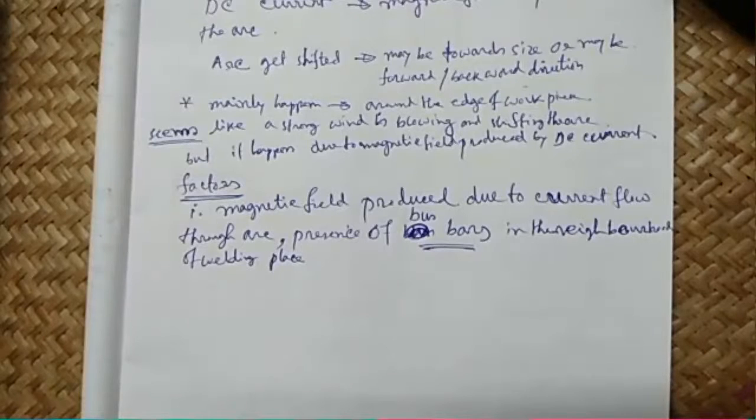When you cut by sawing or milling, you have seen we need to make it smooth by filing it. Otherwise it becomes very dangerous because of the sharp edges produced. Those are basically called burrs. Now as they are kept upwards from the parent metal, they attract the arc and the arc gets bent towards them.